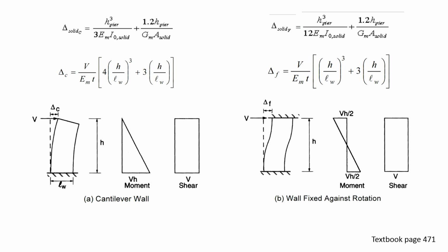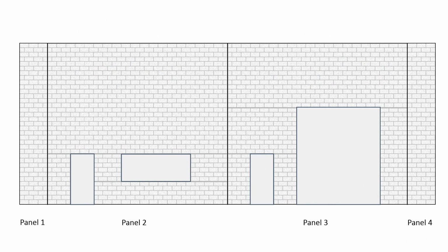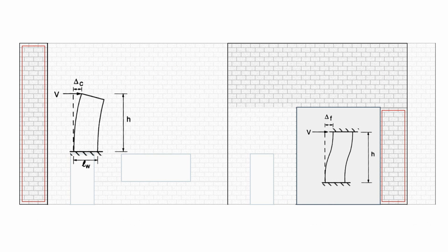Now, if we look at our example shear line, you can see the highlighted pier on the left has no masonry above it, and so it's free to rotate without any sort of restriction from the top of it rotating. Now, if we look at this area on the right, this pier that has a significant area of masonry above it, it would tend to deflect more as a fixed pier because it has all this masonry that is connected,